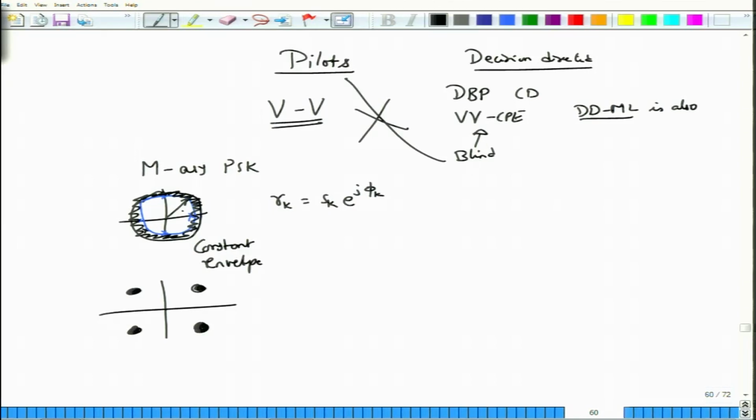So, these are all going to be circles. The signals could lie anywhere in between, but because they are reasonably separated, the BER will be considerably less in this particular case, and these circles are determined by the variance of the noise. Anyway, the point is that in an ideal system, the envelope of the QPSK signals will be constant, and because QPSK is used currently in 100 Gbps systems, this technique is very important for us to learn.